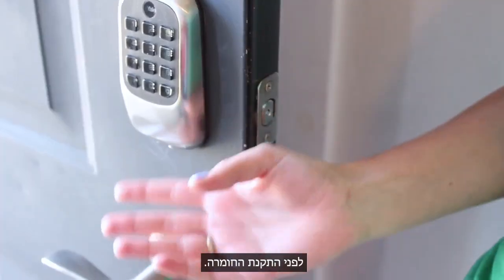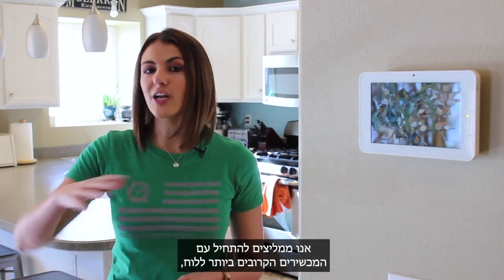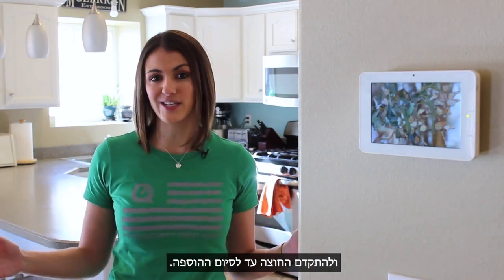Some devices, like door locks, require the device to be within a few feet of the panel in order to pass secure enrollment. So you'll want to include these devices in the network before installing the hardware. You should also be aware of where your devices are as you include them in the network. We recommend starting with the devices closest to the panel first, working outward until inclusion is complete.